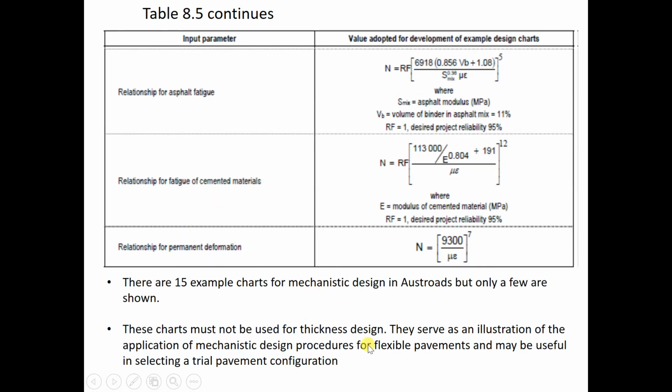But these charts serve as an illustration of the application of the mechanistic design procedure for flexible pavement and may be useful in selecting a trial pavement configuration. It's only useful for selecting a trial pavement configuration. It's not for design.